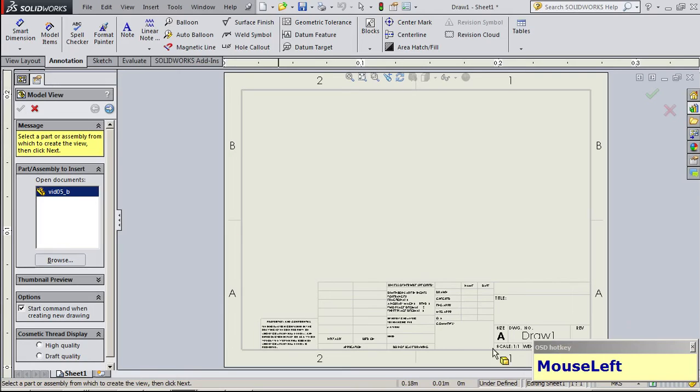If you look at this particular sheet, this actually has a grid available here. It says A, B, and then 1, 2. Because it's a smaller sheet, you don't have too many of the grid points. This is basically used to map your feature. So you might want to put in your note, you're going to say B1, there is some intrinsic feature, then take care of that particular feature.